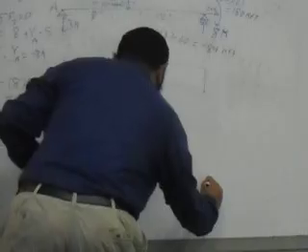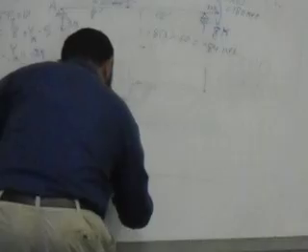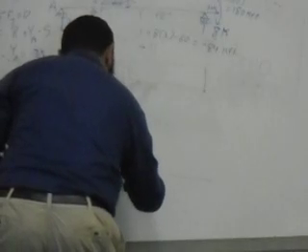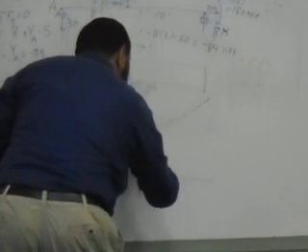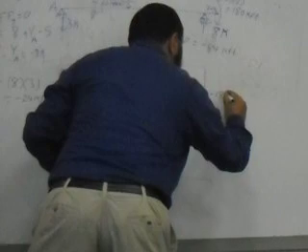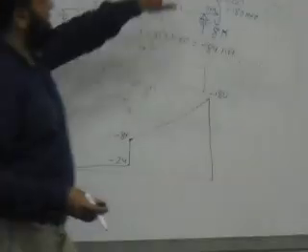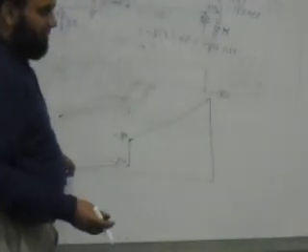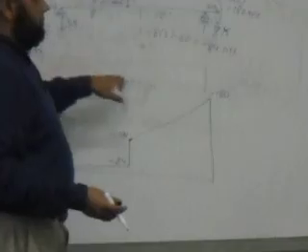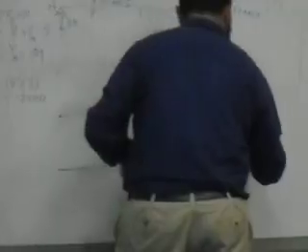So this was negative 24. Then it's negative 84. Then I'll have a negative 1 equal. And you notice something very interesting. If I take a section after C, it's 0, so it goes down to 0. You notice something very interesting, that the slope of this line is different than that line, because there are different shear forces. And we said that the shear force is the derivative of the bending moment diagram.